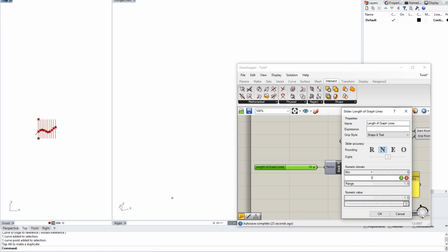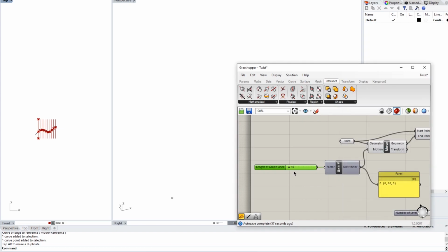So what I will do is change this upper limit to 100, maybe 300. Okay, and as I press OK, over here we see a floating number type, which means decimals. We have integers, and we have even numbers and odd numbers. What this does is limit the selection of values within that maximum and minimum range to a certain format. So we would like integers this time.